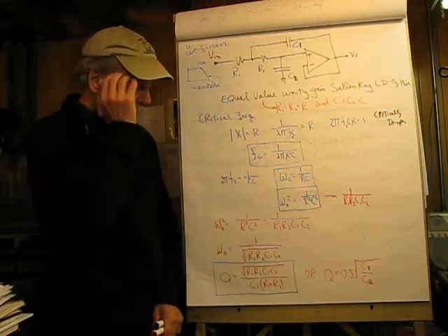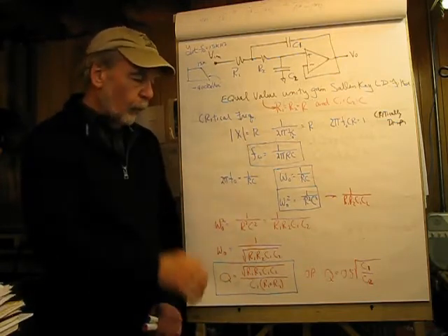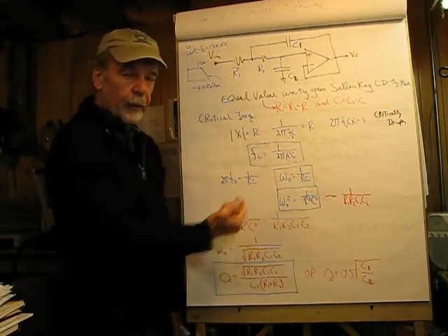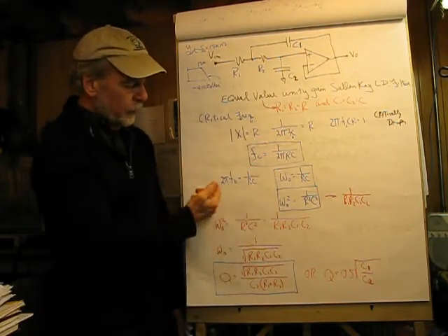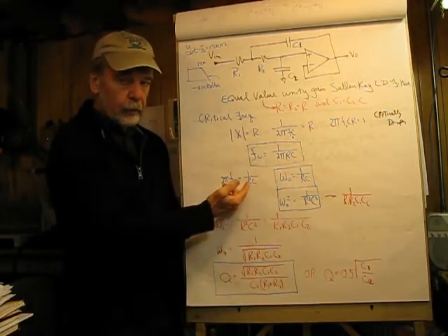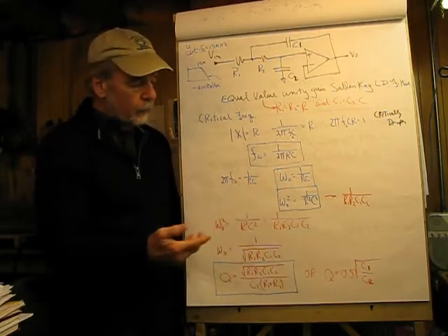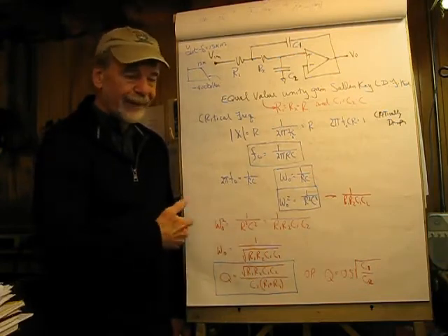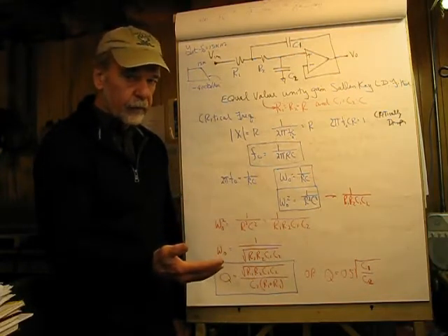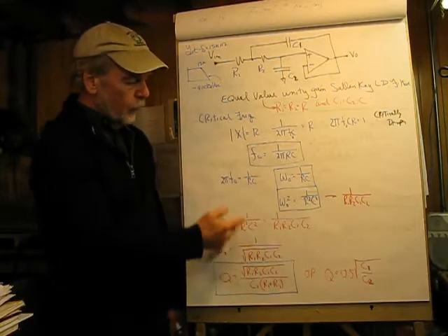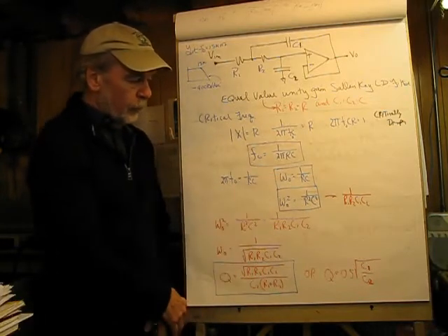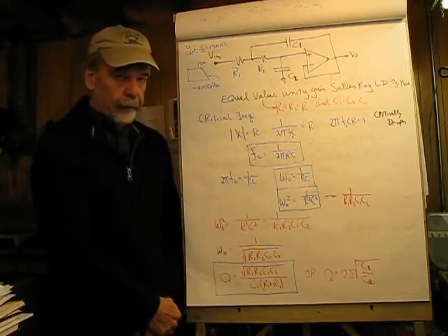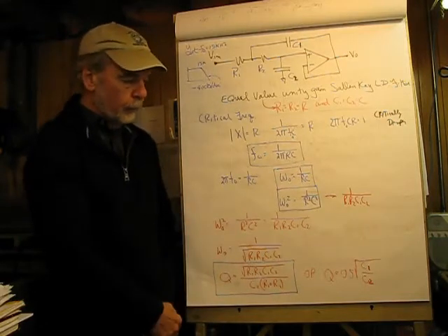Now, we're dealing a lot with omega, so what I want to do here is divide both sides by 2 pi, which will give me 2 pi F sub 0 equals 1 over RC. And it's important that you're comfortable with omega 0, because lots of the stuff uses omega instead of 2 pi F. So in doing that, as you can see, omega 0 equals 1 over RC, and then I'm going to be needing an omega 0 squared term.